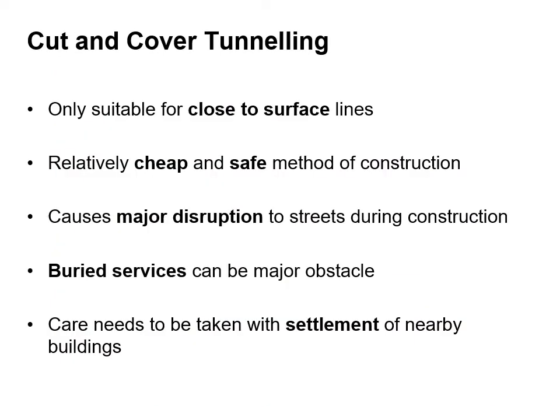So cut and cover tunnelling techniques are only suitable for close to surface lines. They're a relatively cheap and safe method of construction. It causes major disruption to the streets during the process. Buried services can be a major obstacle, and care needs to be taken with the settlement of nearby buildings, and this was quite a significant problem in Amsterdam with the North-South Metro line.